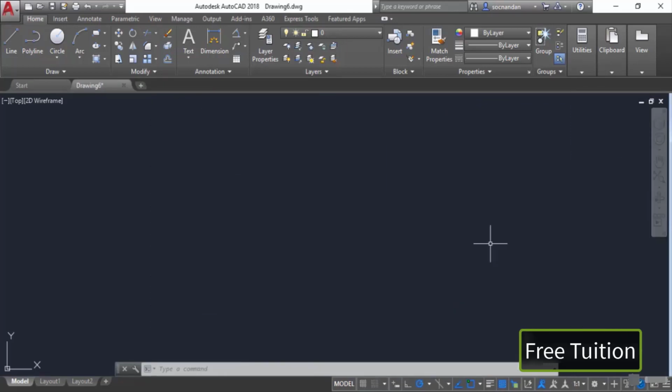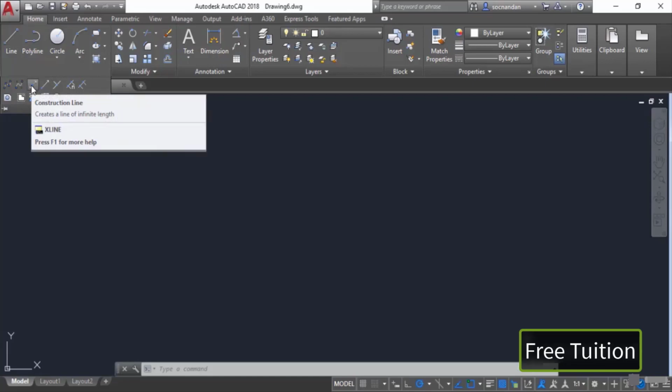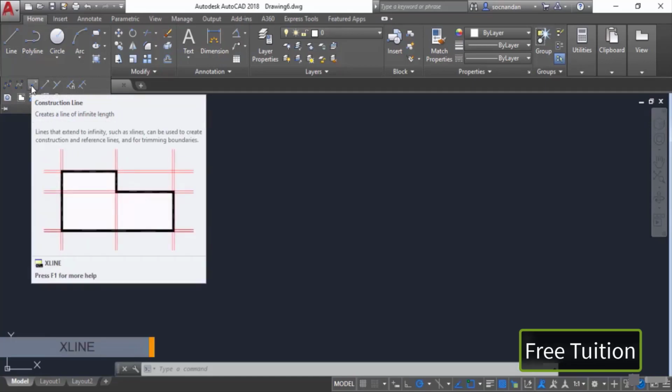In this video, I will tell you about the construction line and array command of AutoCAD. So construction lines are simply lines which are used for helping to make other geometries, and they are infinite lines. So to make the construction line, go to the draw panel, expand it, and now select this option here. So here we have this construction line. You can also use its command equivalent XLINE.